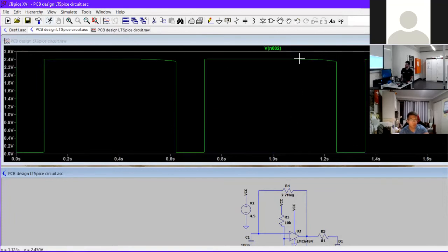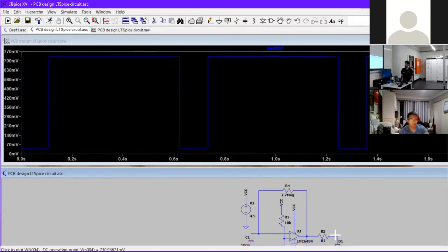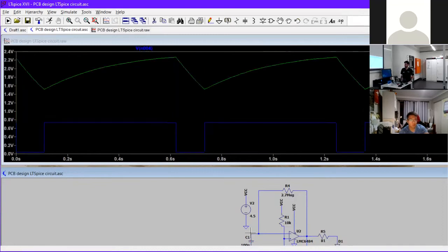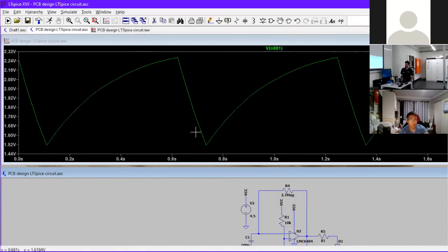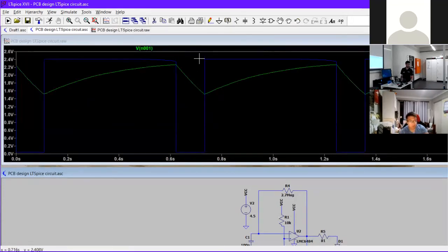But you also notice we're getting a bit of drop, a bit of slew behavior here. This is our capacitor being too big, so it's not cleanly falling off. If you change it to like 50 nano, would it be better? If you made it smaller, yeah. We can also have a look at what our capacitor is actually doing over here. Charging, discharging, charging, discharging. Then the output wave is matching the discharges.